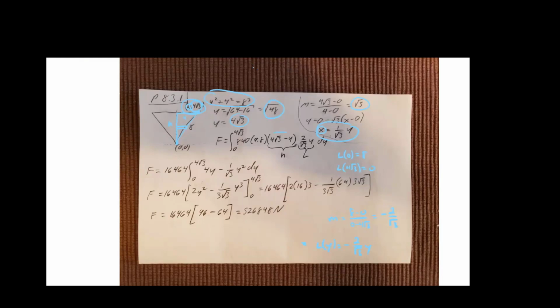Yeah, this is a situation like what I was talking about. If you don't treat the top of the tank as y equals 0, then you have to make your h be something else. The h of y would not simply be y. So with the convention that I use, you kind of avoid that, having to figure out what that h of y actually is.